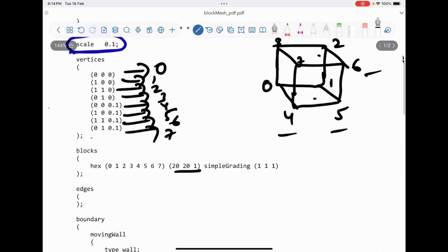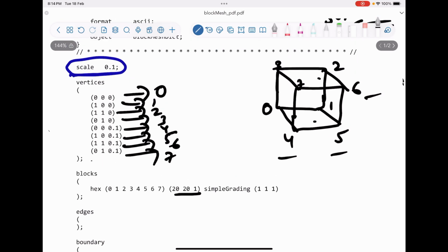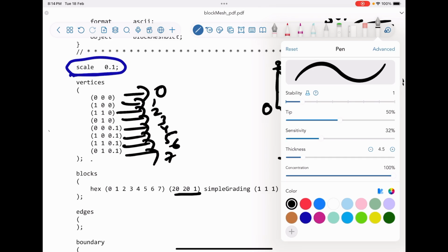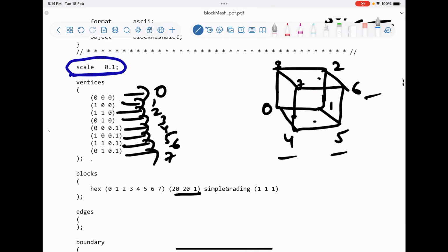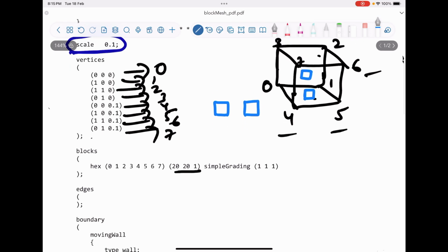Now one more important point is how we are defining this. OpenFOAM always makes the boxes inside the boxes which I have defined. It is always making the boxes like this, either in the anti-clockwise direction or in the clockwise direction. Did you get it? So it will not make the diagonal. For example, how I have given the naming, if you wanted to make the finer mesh.